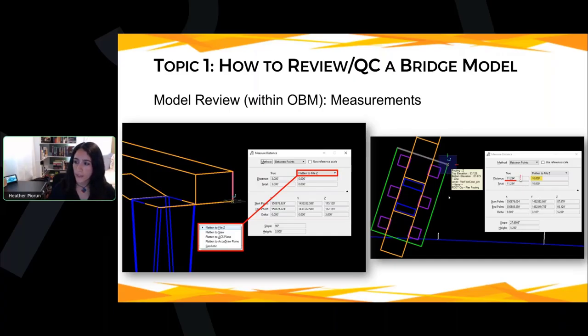So again, if you're in top view here, you might end up snapping to 2 points at 2 different elevations, which you can see happened here, right? This says my true dimension is 11.294, which, if I look at that, I would have that red flag that's like, that footing is probably not 11.294 feet wide. Then you could take a look over to this flatten to Z and see, oh yeah, that makes more sense, 10, right?